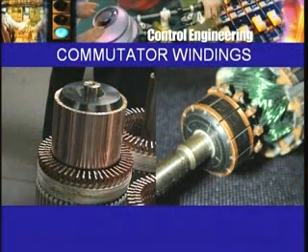The current in the field winding produces the magnetic field, and the conductors which constitute the armature winding, when they carry a current, interact with the magnetic field, producing a force or a torque, and that's how the motor rotates. Of course, as you know, because I'm talking about a DC motor, what is called a commutator is required.